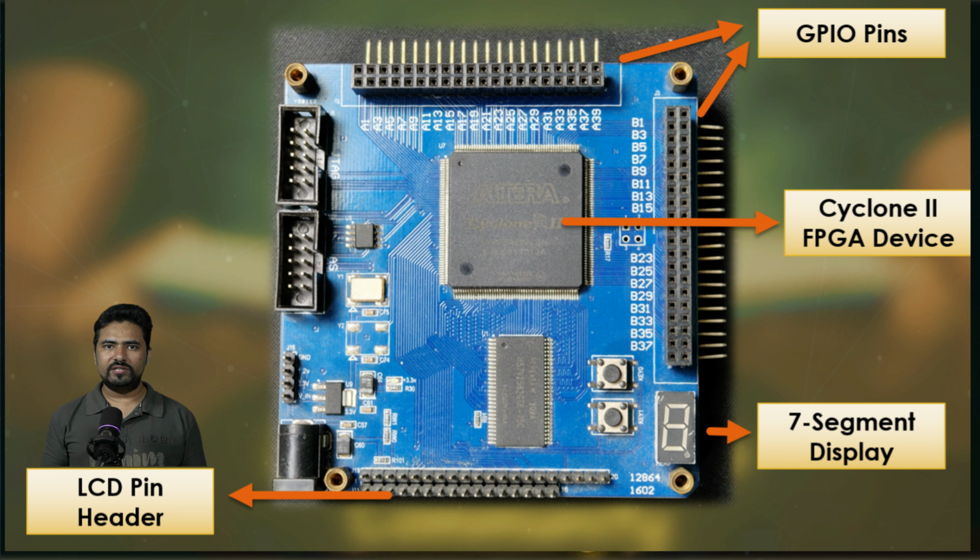When you write your VHDL code, it exists in the text editor. However, on the physical device, it's implemented using registers, combinational logic, and gates such as AND gate, OR gate, NOT gate, etc. And all these things are connected by some wiring, right? The netlist viewer provides a visual representation of this hardware realization, helping you to understand how the physical hardware performs the functions which you are describing in the VHDL.